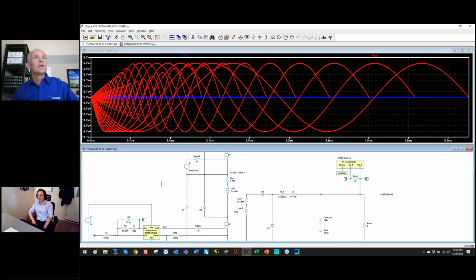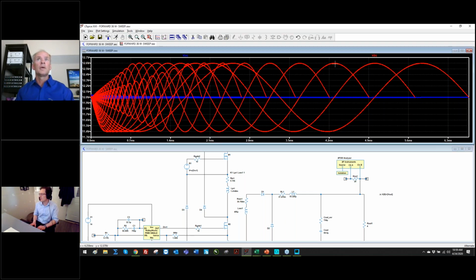It has finished. Now, interestingly enough, LT Spice has always had the capability of sweeping loops like this, probably for about 10 years now. It's only just become viable because of the speed of the computers, the multi-core threading, and just the efficiency of the program. Notice here on the red waveform, you can see this contour. If here it's injecting a fixed signal, and then at some point it starts dropping the size of the injected signal.